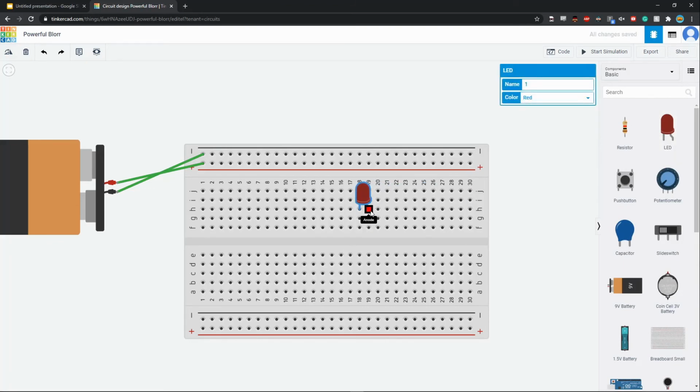The longer pin of the LED is the anode, so that connects to a positive end. We want electrons going from the battery positive through here to the long side of the LED, through the LED, right? So how do we finish the circuit? We need to complete a circuit, otherwise electricity will not flow. So what we could do is go from the negative end. Everything here is connected, so go from the negative end to the negative end here, and that connects the circuit: positive here, through the LED, through here, and then goes down, right? If you try that, that's going to blow up the LED.